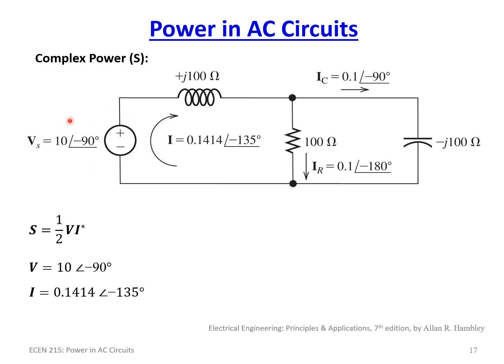So what is being supplied by this power supply? By just taking V and I, multiplying the two together, we're going to get the supplied power, but we first need to take the conjugate. So I conjugate in this case is just changing the direction on the phase angle. Instead of minus 135 degrees, it's now positive 135 degrees. That's all we had to do to take the conjugate of this.